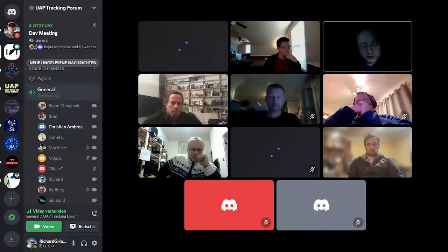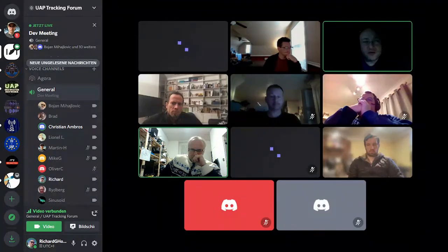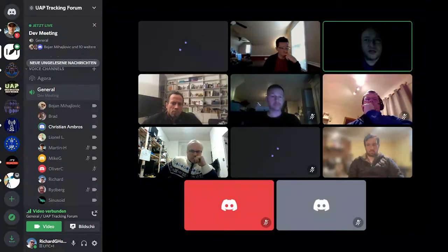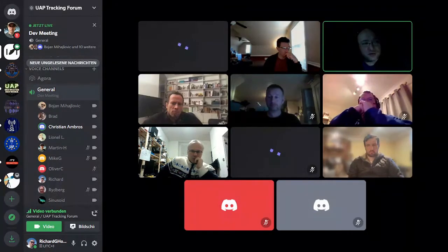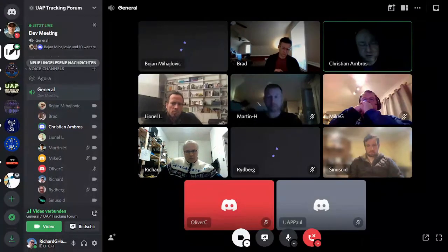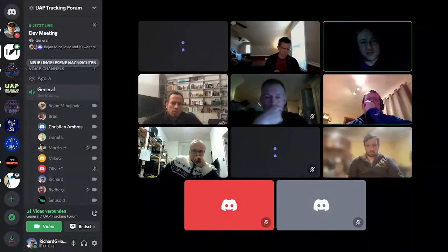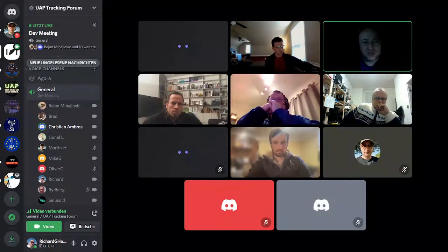No, not just the microcontroller. The optics needs it because we do not want to have dew on it. The camera needs it because it needs stable conditions. It must be dry, because if the temperature falls below 0, humidity will freeze, and this is bad for the chip. Normally in astronomy, cameras have a glass plate with a heater so humidity can't freeze on the glass cover of the chip. And you need it for the electronics as well. Having stable conditions means no dew on the cover, no dew inside, and everything can work under controlled conditions.